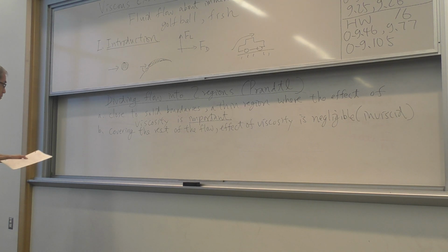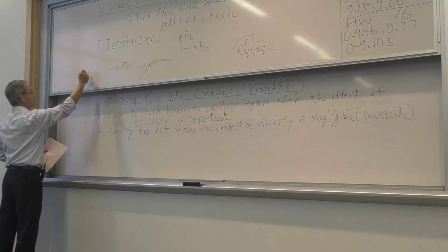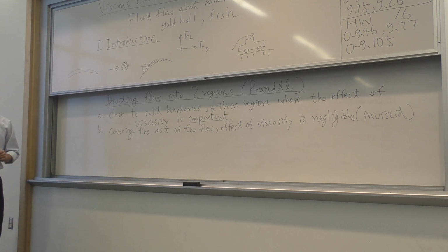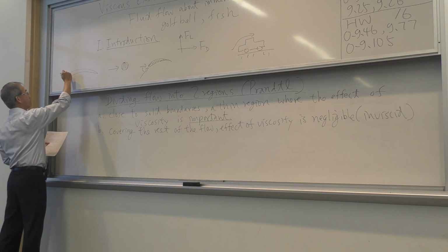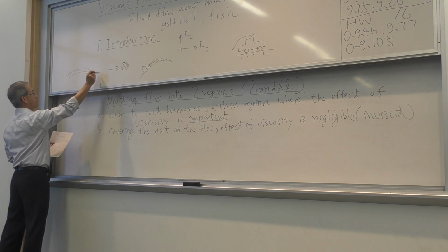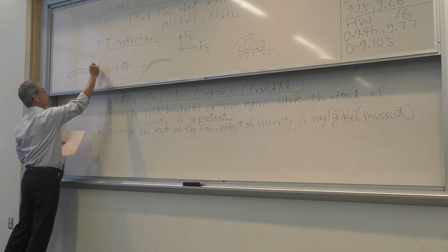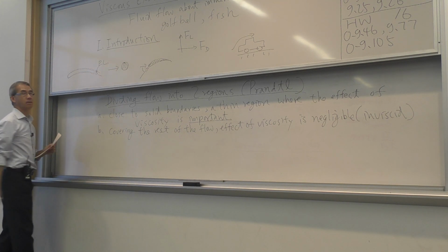So now all of a sudden, I can look at an airfoil, where I'm looking at different shapes to generate more lift and also less drag. I can analyze this problem by pretending there's an invisible layer wrapping around the lower and upper surface, which I will call BL, standing for boundary layer.